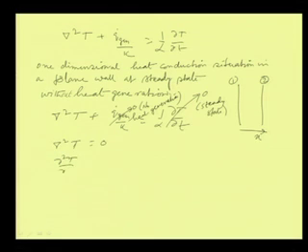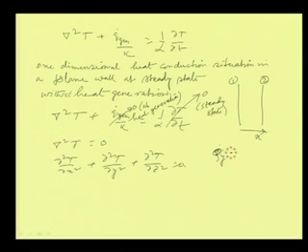Now, if we remember what this del square T term is, it is del square T by del x square plus del square T by del y square plus del square T by del z square equal to 0. Now, we are telling that it is a one dimensional heat conduction, that means there is no heat transport along y and z direction, that means there is no gradient along y and z direction. Because we know that if heat transfer has to be there in y direction, then q dot y is equal to minus k into del T by del y.